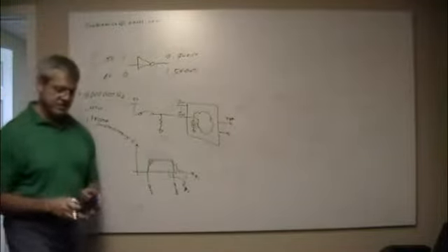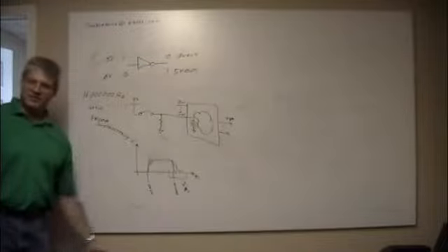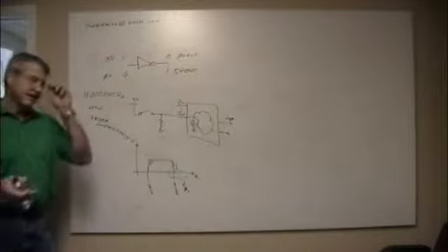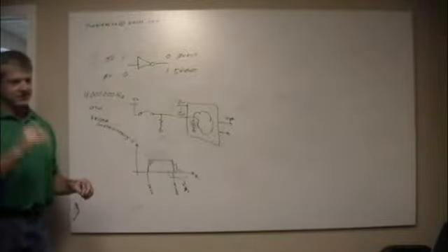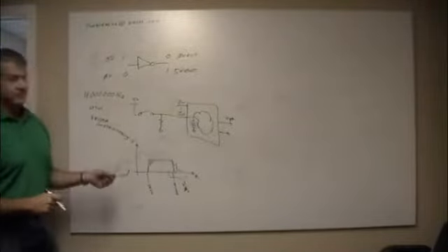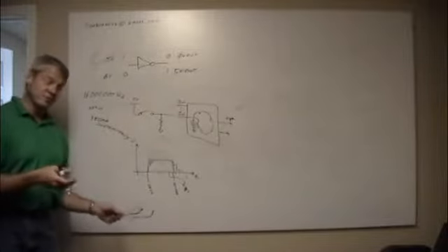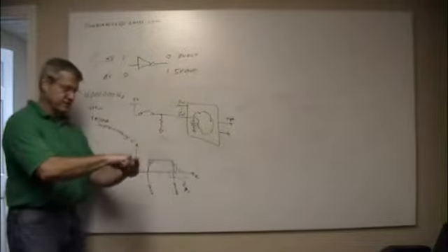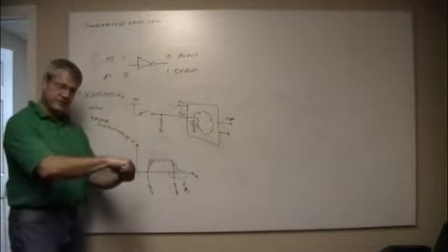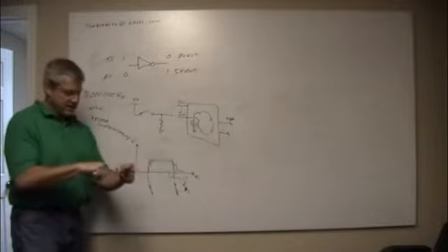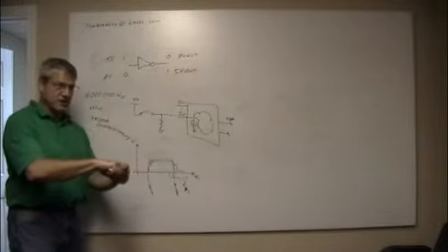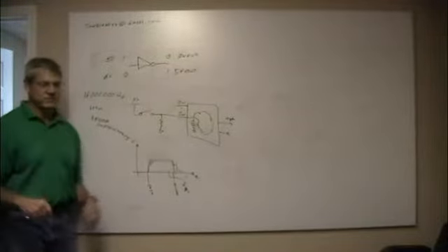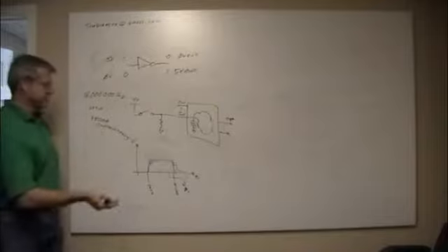Now, say I want to make a light bulb turn on when this happens, and turn off when it's not. You don't care there, I can't see that with my eye. But this is something I've had to do here at work. I've got an actuator pushing something until it hits a limit switch, and I don't want it to go any further. When it gets there, I want it to stop. It goes bouncity, bounce, bounce: it's there, it's not there, it's there, it's not there, and then it went too far. So we had to debounce it. It's called debouncing it.